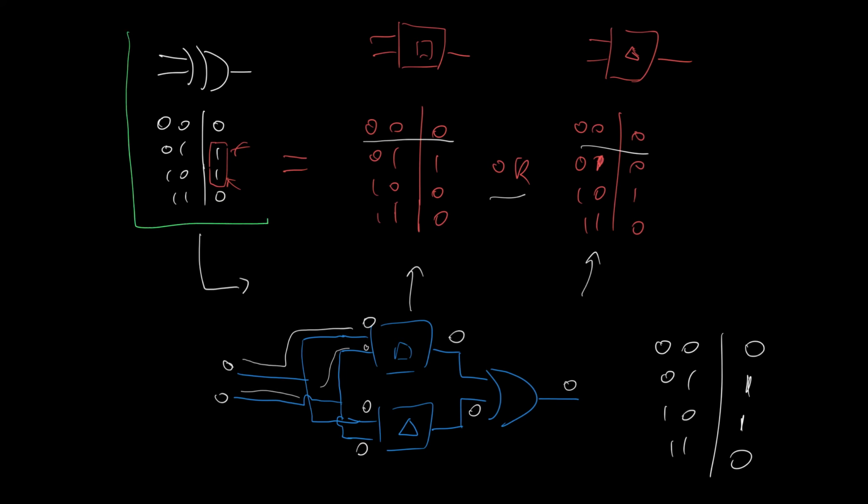The next step is to write each of these gates using only AND gates. Now in general we can't do this, but because each of these has the very special property that there's only a single 1 at the output, it turns out that we can do it. Well, almost. I told a small lie. We have to also use NOT gates. And once we see this, this makes perfect sense. First, let us remember what the truth table is of an AND gate.